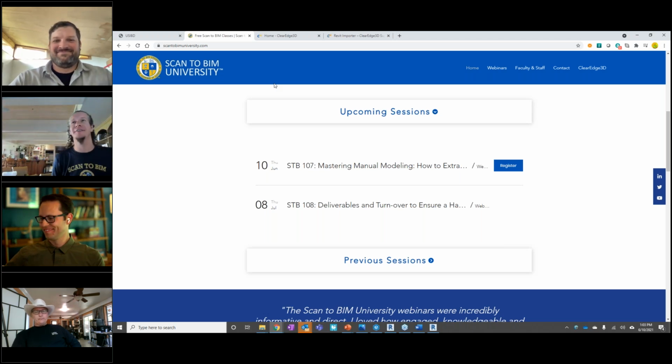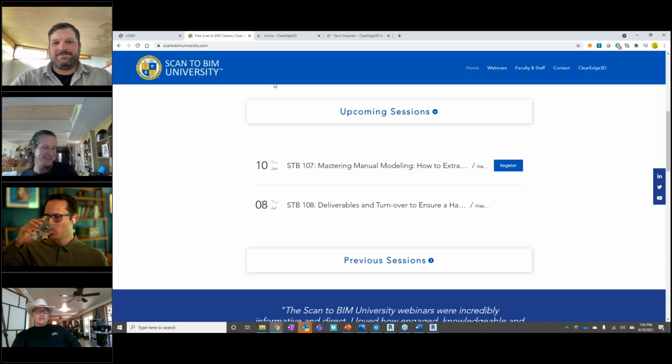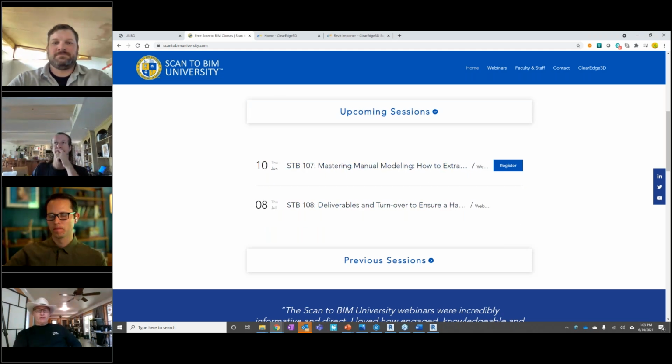Larry, go. Well, just adding to what you and Sylvia said, one of the things I tell the junior modelers is, if you have to make a decision as far as where to place the wall, because it's not orthogonal, it's leaning, it's not plumb, always err toward giving them less space in the room or wherever it's critical.